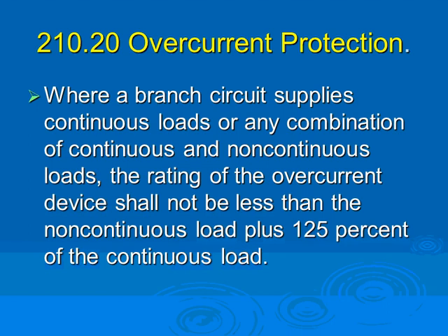So I do residential calc and commercial calculation. When you size a service for a building, that's how you do it. You take all your lights, multiply them by 1.25, assuming continuous load. All your receptacles are non-continuous load, so you add them at face value, after also applying a derating factor. So that's how we size your overcurrent protection device.